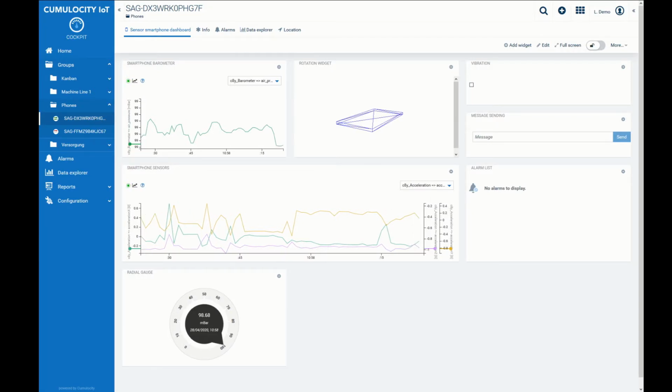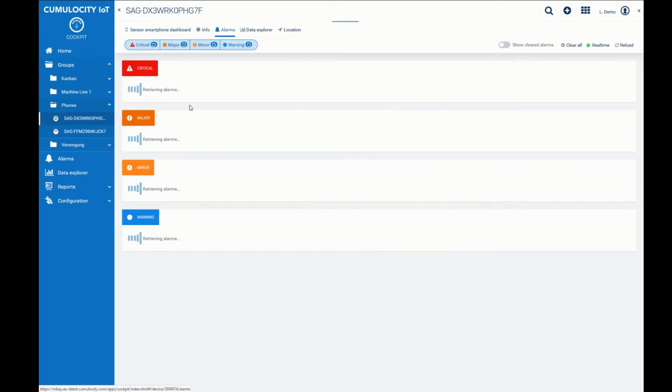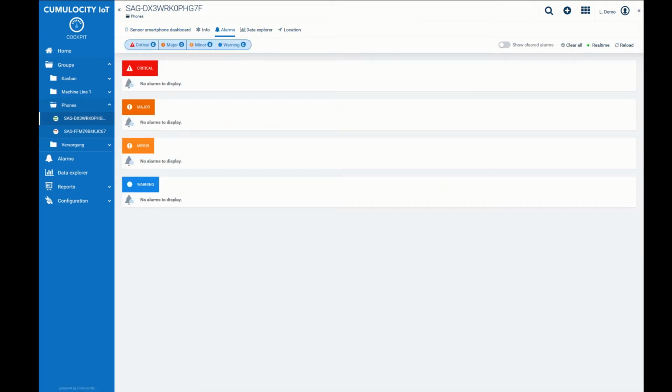Great. Now let's talk about notifications and integration. Additionally, as a responsible person for those smart devices, I want to make sure that in case I am not available, surely someone will be addressed and will look at the popped up issues. In that case, I will show you what the escalation program looks like in the Cumulocity IoT alarming list. Cumulocity IoT has a built-in functionality to escalate an alarm if it was not acknowledged and the issue not fixed.